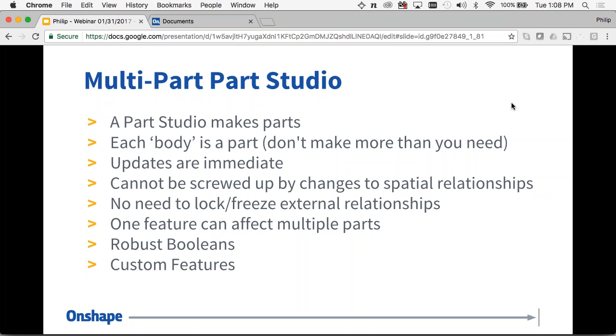In almost every CAD system that you're used to, if the result of any Boolean operation is anything other than one discrete body, you're going to get an error message or a failure. We can take advantage of that within Onshape to come up with some very powerful regeneration capabilities. And then we will look at a quick custom feature, and custom features, as you know, work within part studios.